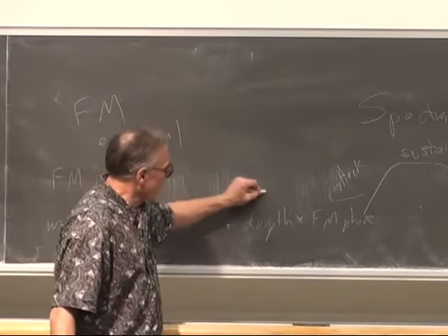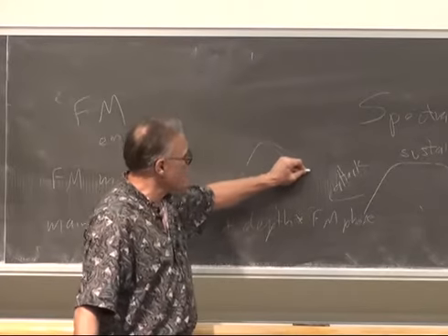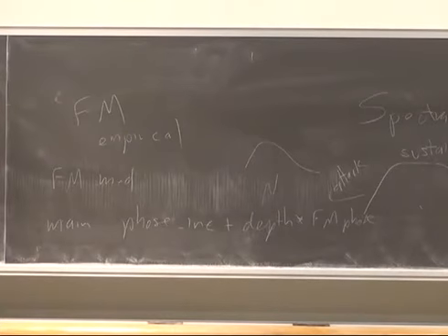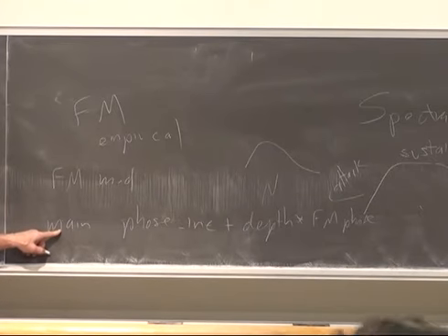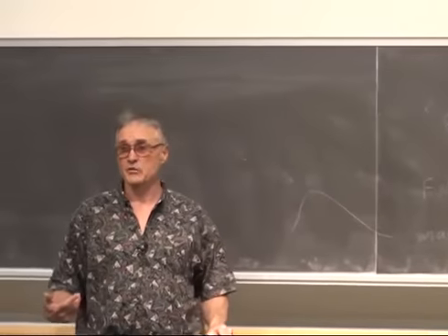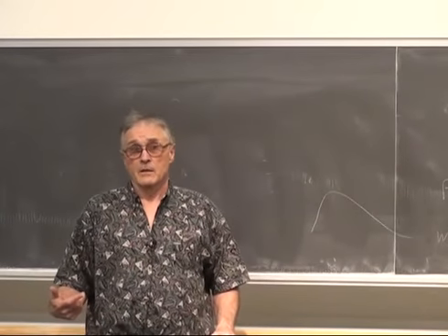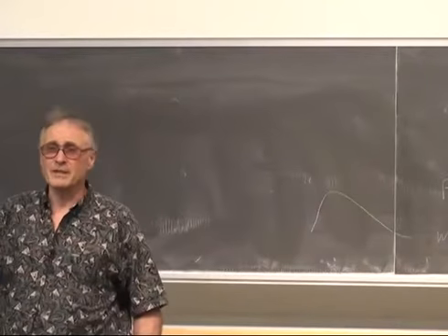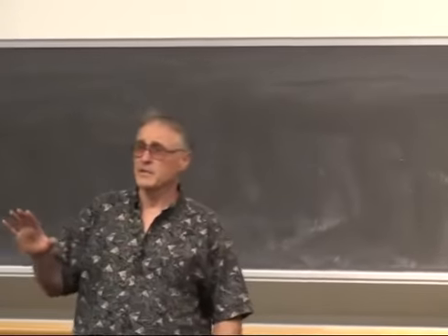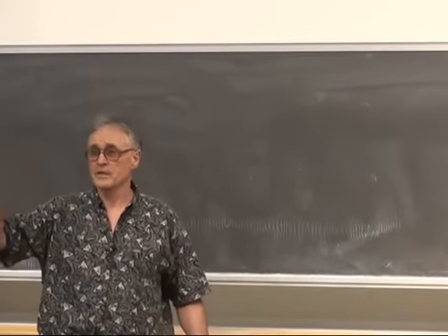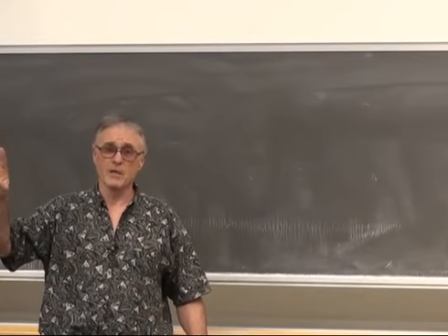The depth parameter is also an exponential rise and fall. You're going to get an FM modulation depth which has a transient envelope, and the main sine wave will also be amplitude modulated with an exponential rise and fall, and maybe a sustain. So you get a pretty interesting, complicated, sometimes ugly, sometimes ridiculous sound out of the system for the cost of 2 direct digital synthesis units and some multiplies.